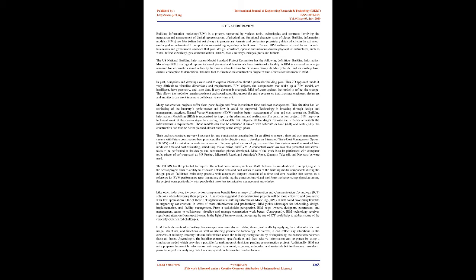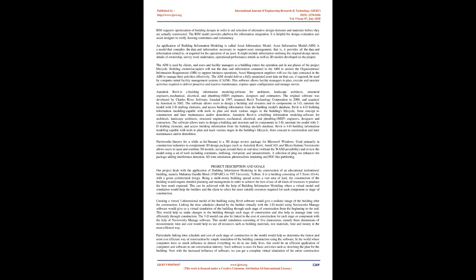We created sets for each building component like flooring, walls, windows, doors, and ceiling for each floor. We then linked the sets to the activities and their respective dates to create the time constraint simulation. Creating this sort of time constraint simulation will help us get a virtual idea or image of the completion of the entire project part by part and helps manage the construction more efficiently and precisely.